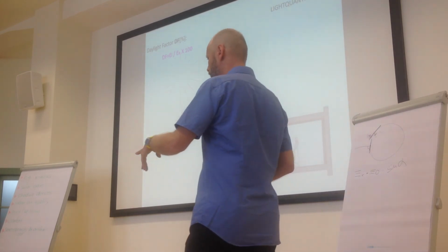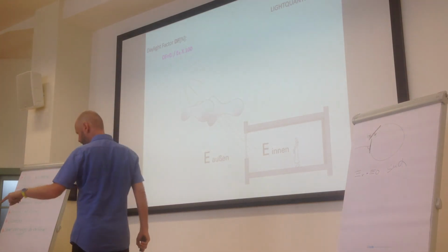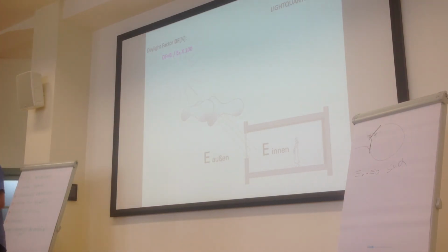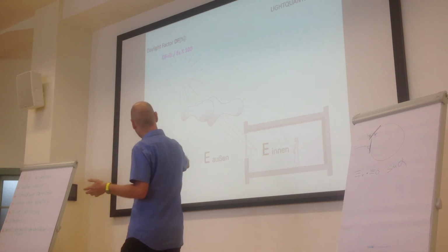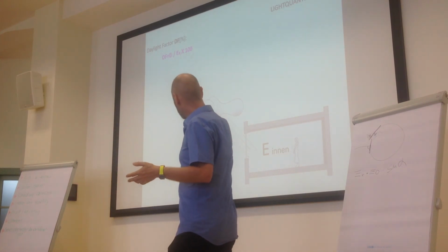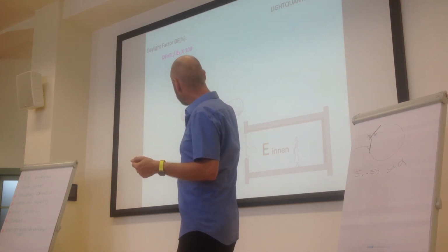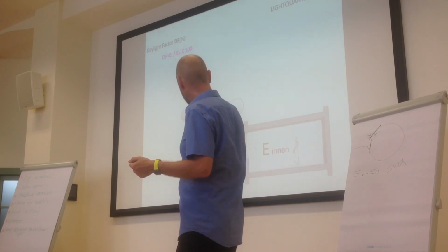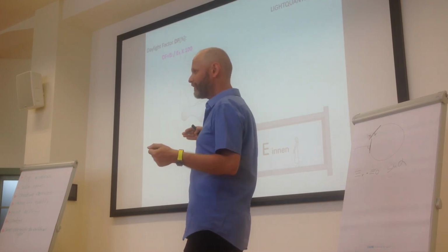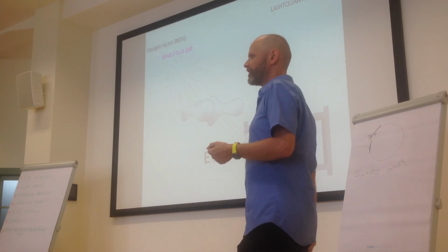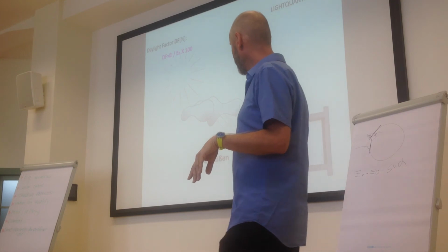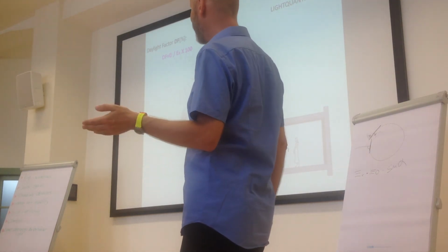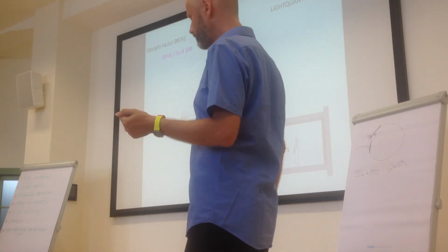So we take our measuring tools, I have prepared some here, and we will use them in the afternoon, and we are able, in a very, very simple way, to measure the lux level outside and inside. And by using these values, the interior and the exterior lux level, we can quantify the daylight factor. And if somebody asks you, how much daylight do you have inside your building? You can answer this question by naming the daylight factor.